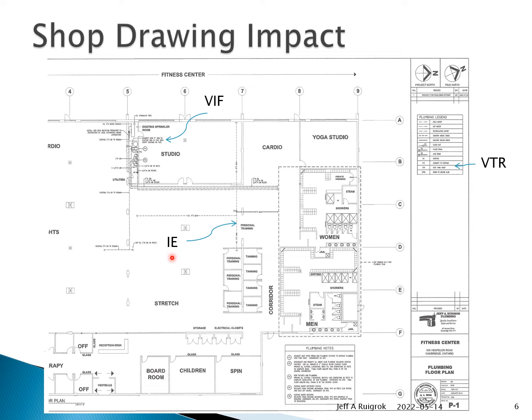This building was an older building, so I had to find the invert elevation for the main drain. And that was for a number of reasons, including, was it deep enough below the building that I could rise up with my fall, or my slope, sorry, all the way to these farther fixtures. Anyway, so I located the invert elevation, and then verify in field was also a concept. I guess I hadn't given him enough information, so he took a guess at something. Doesn't matter what that something is, but he felt it should be verified in field, so he put a note there. And then, of course, vent through roof is something right out of your textbook. Anyway, so that's some common aspects of what you'll see on design intent.